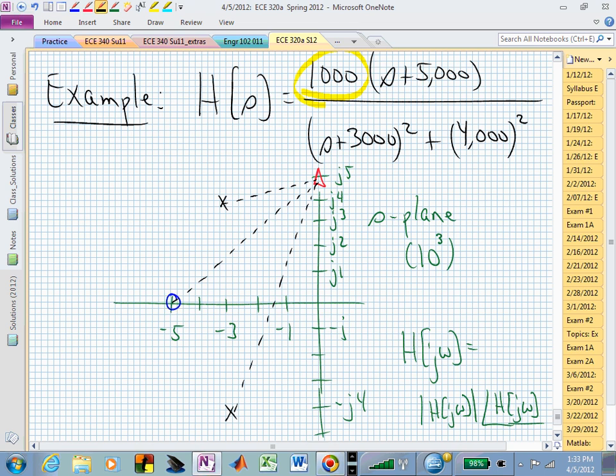That's the angle that I'm going to have associated with that pole. If I now come down to minus 5,000 for my 0, and I'm measuring that angle with respect to the horizontal real axis or real line each time, I now have to turn a little bit wider to see j5,000. And the angle of the 0 is this angle. And if you've drawn this accurately to scale, you could get your protractor out and measure that angle. Or you could do it on your calculator, and you could say inverse tangent of 5 divided by 5. And that should be 45 degrees.